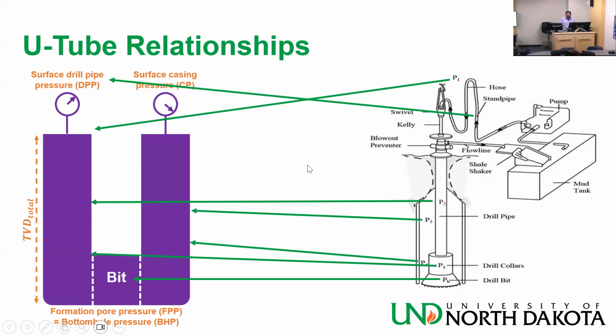So how do you cater for those pressures that you're losing due to friction? Do you mean how can I measure it? Yeah, how can you make sure that you reduce the losses or counter them? Well, reducing the loss to friction is by making the conduit bigger. That means if I can drill my hole bigger and use a smaller pipe inside, or bigger pipe inside, sorry, there's going to be less friction. But I can't do much about it.